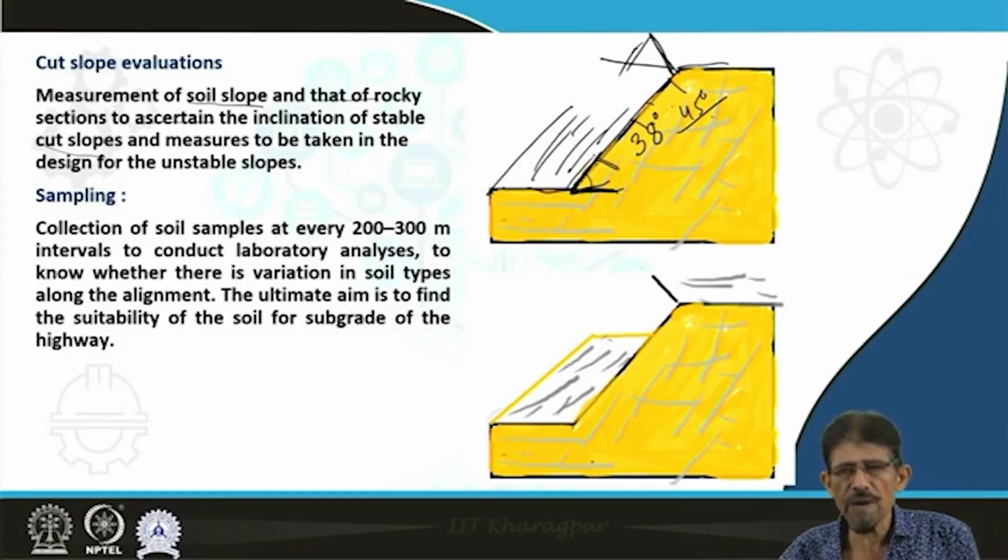In case of rocks, we are going to put as high as possible, even more than 60-70 degrees. 60 degrees is a minimum, 70-80 degrees, depending on the nature. If the rock mass is weaker in nature, poor in quality, then we cannot give more inclination, so we are confined to 40 degrees, 50 degrees, etc.